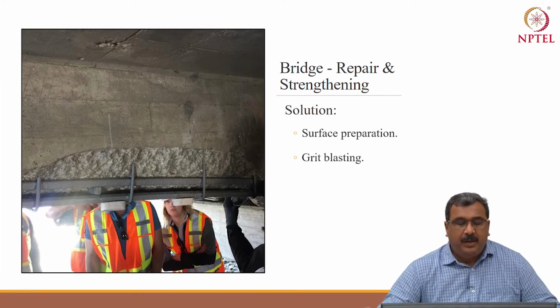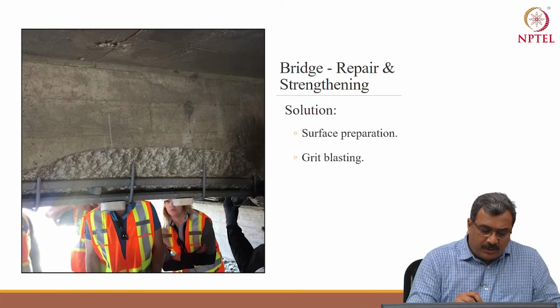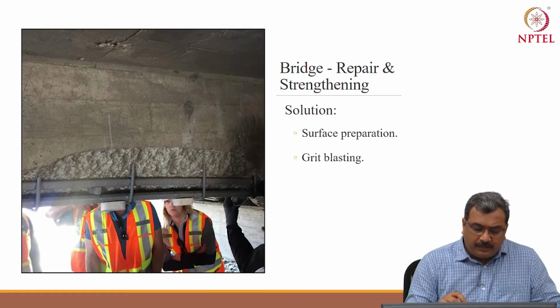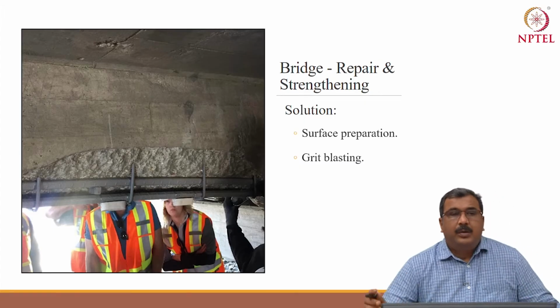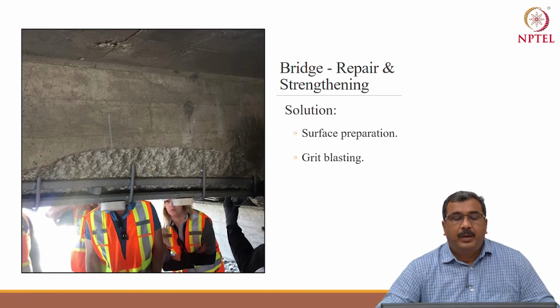New rebar has been planted and sacrificial anodes, this white anode, are being tied to the rebar based on the design of steel density of the bridge, considering a life of 25 years for the anodes.